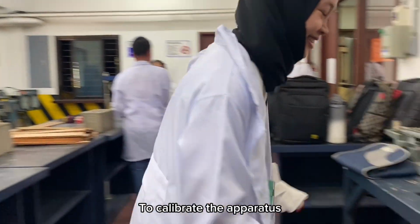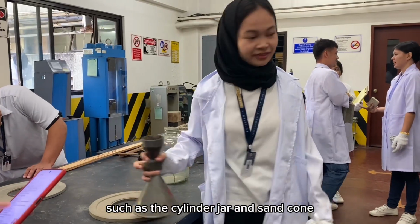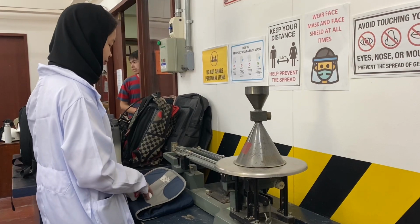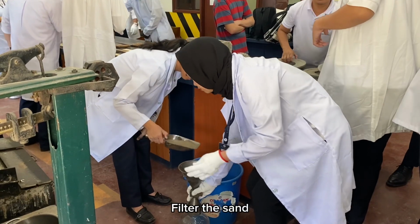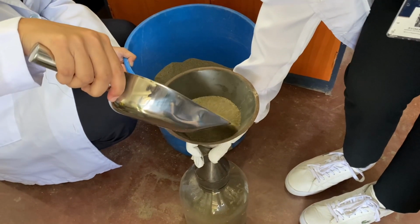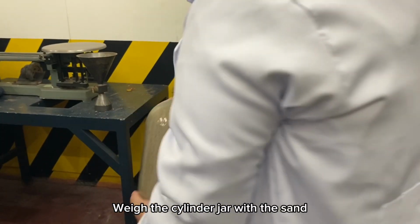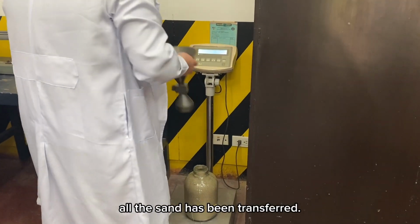To calibrate the apparatus, begin by measuring the weight of each piece of equipment, such as the cylinder jar, sand cone, filter the sand and then carefully transfer it into the cylinder jar. Weigh the cylinder jar with the sand and repeat this process until all of the sand has been transferred.